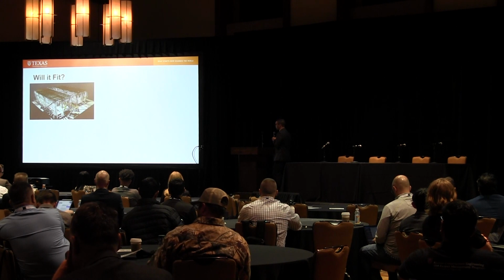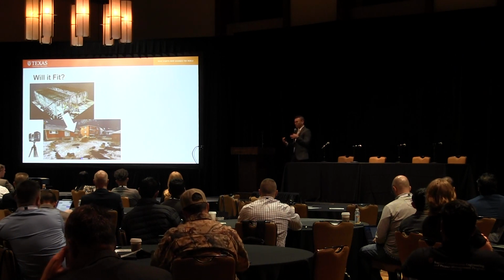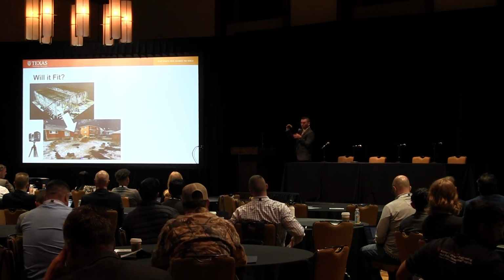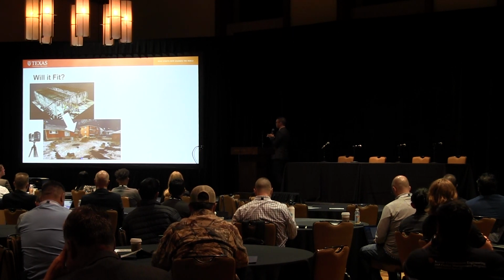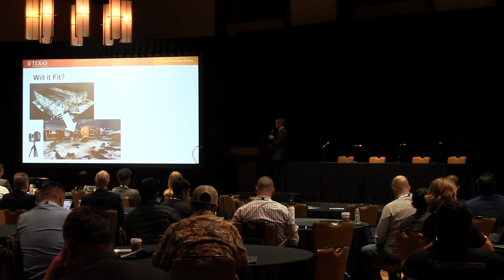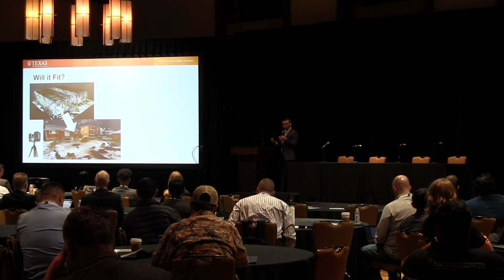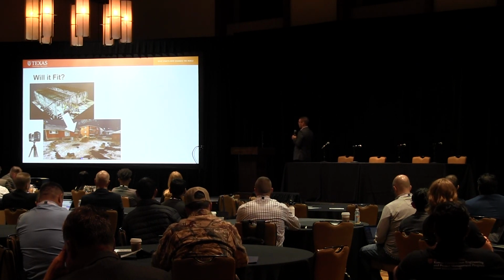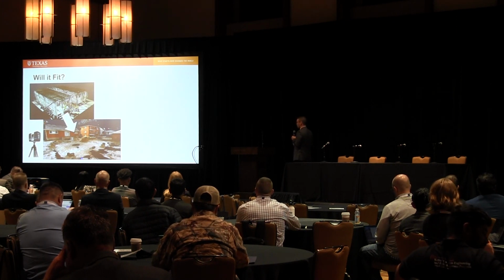And to show some of the work that I've been involved in, here's a simple project where I was working in off-site construction, where the question was, how do we ensure not necessarily that what was being done in the factory was built to a suitable accuracy, but when we brought those units to the job site, how do we know that those interfaces at the job site are going to correspond to where they need to be? And so that's where taking and comparing scans of these two environments ahead of time, you can perform virtual fit up and make any corrections before you show up at the job site, where the cost and the schedule implications are obviously a lot more impactful if you're going to have problems.